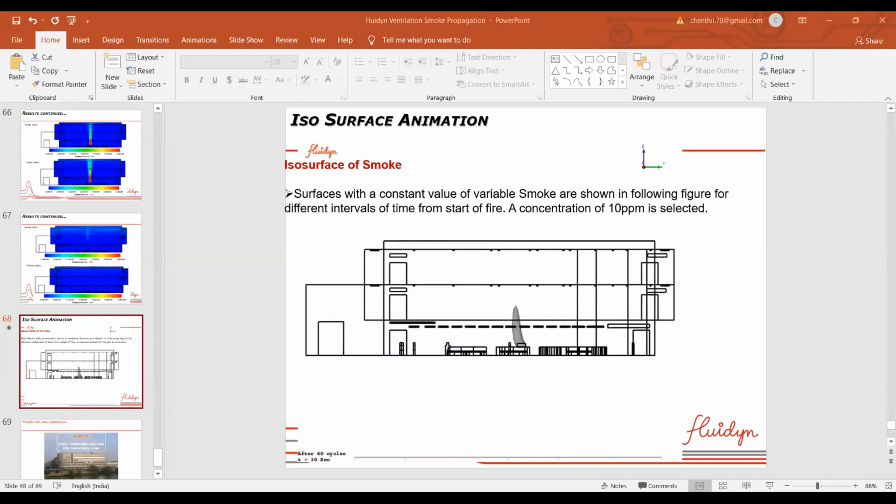Other than that, there are fire definitions, like a fire if you define. Basically, in this platform, all problem definitions will be taken through the geometry level. So for example, leakage. It will take a point source or volume source or surface source, that doesn't matter. If you introduce it, once we load this geometry in the GUI, these boundary conditions are automatically identified. Okay, this category belongs to extractor. So from the user's point of view, you have to specify only the flow rate, the extraction rate.